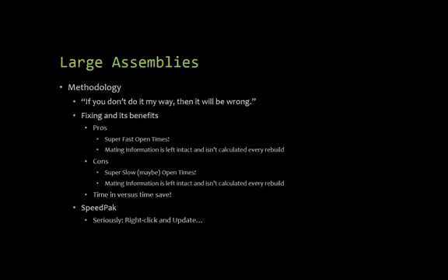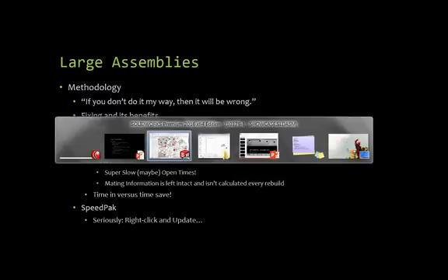Fair enough? So I am one of those people that as I go through, I want to always look for efficiencies. I'm always looking at a time debt and everything like that. For me, the time debt's good for me. I'm saving an hour. That's going to take me 10 minutes to update things. I'm fine with that. The other thing that you run into is, as far as the time debt, there's a prodigious use of configurations in here as well. So while I'm loading a 5,600 piece assembly, if you look at it, there's only 300 unique files that are being loaded in. And then out of that, there's only like 120 actual part files being loaded in. And it's only because, in a case like this, configurations work great.